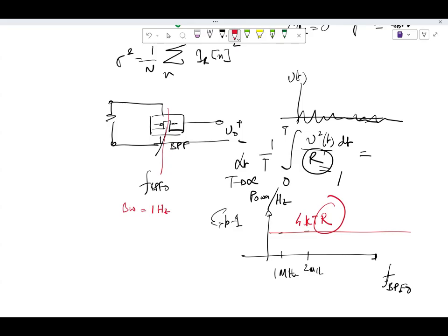This curve tells you that if you have a certain value of R, it is going to give you a power per hertz, regardless of where you observe it on the frequency axis, and the value will be exactly equal to 4kTR. The important thing to note is that it doesn't matter how you have made that R. You have used copper, silicon, Apple, it doesn't matter. If it's a certain value, this will be your noise. It's independent of the material, so that itself is a fascinating thing.